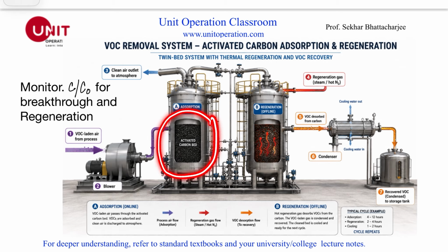But what happens after some time? Of course, this gets spent. That means all its absorption capacity has been totally utilized. And after that point, whatever concentration comes in, the same concentration goes out. So we, of course, don't do that. So what we would like to do is regenerate this one. That's why two beds are used in tandem here. So let's say this is now working, and this is now being used for regeneration. After this is regenerated, this will be working, and the other will be regenerated. That's the way it works.